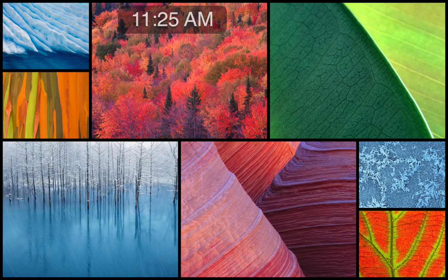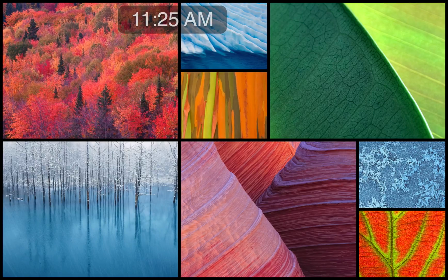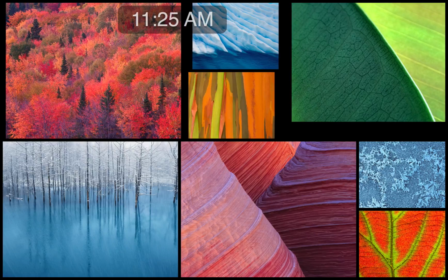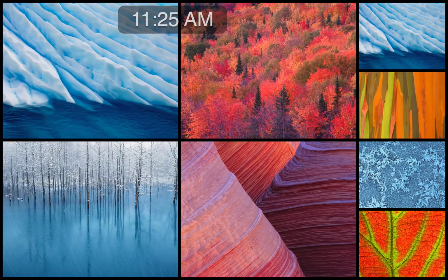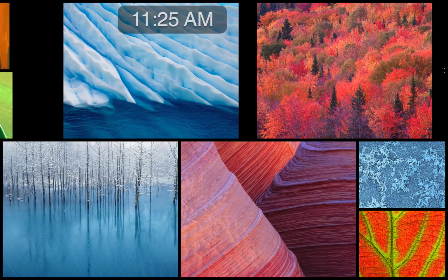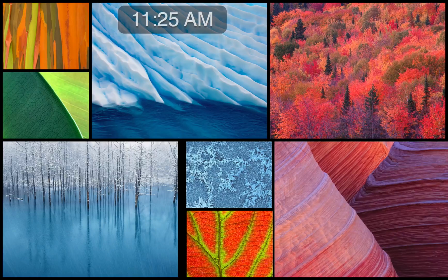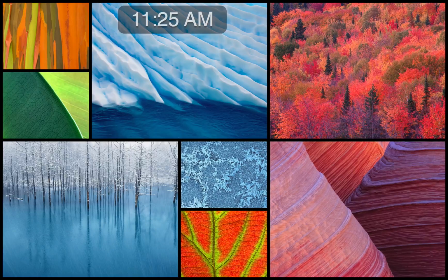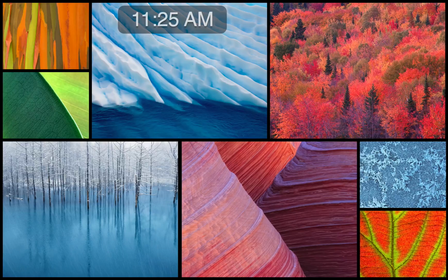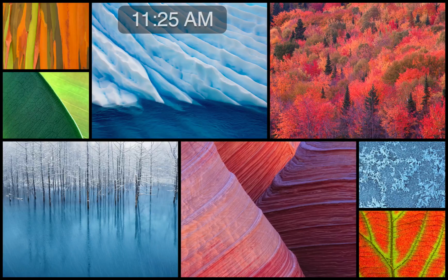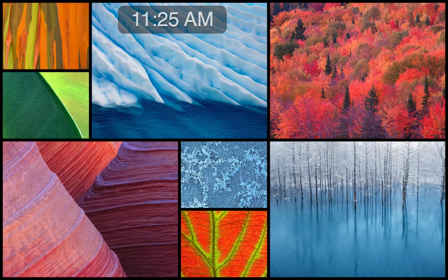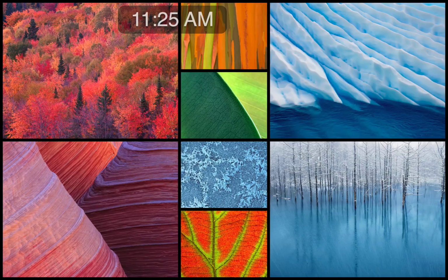Something's wrong with my wall. This does not appear to be 3.5 inches away. Yep. Okay. So this reference plane right here is in the wrong place, and this grid line. So I'm just going to click on it. This is a good trick also. When you want to move something at a specific distance, you click on it, and then these dimensions automatically show up. And then you could say, I want that dimension off of this guy, and I want it to be 3.5 inches. And then it'll just move it to the correct place.